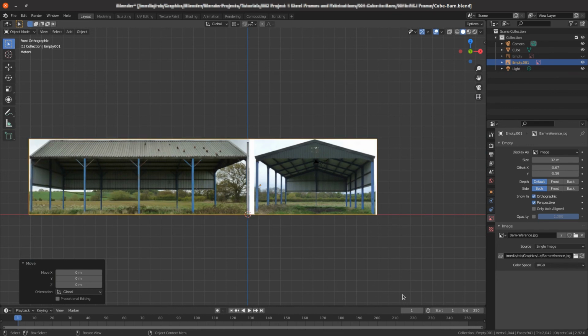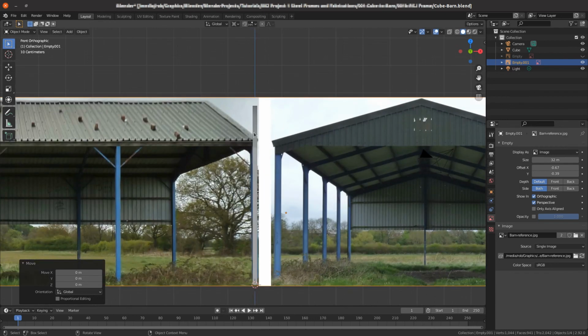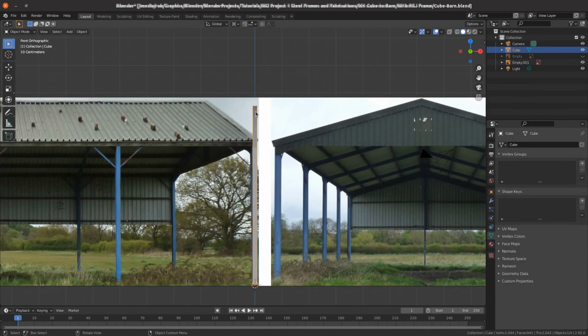We can use a modifier for that, which non-destructively copies the first part of the model. So if we select again what is the cube object, I'm going to change the name of that, double click on it in the outliner and just call it RSJ. That helps keep it organised.